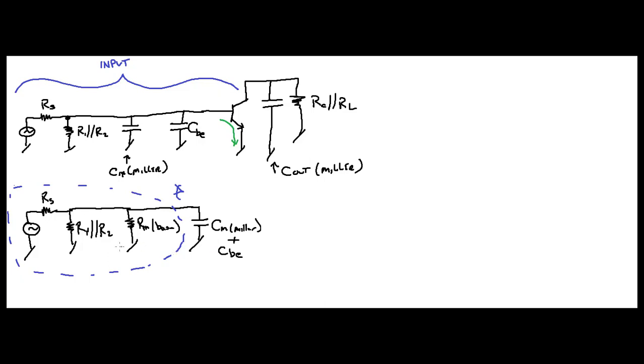So if you think about it, when you Thevenize something, remember for resistance, you replace your source with a short, just a wire, right? So when you do that, RS is also going to ground, isn't it? So all these resistors are in parallel and they're all going to ground, right?